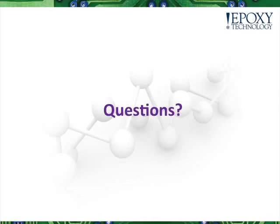And next up, what is the maximum depth of cure for most UV systems? And what is the maximum depth of cure for hybrids? Well, that's going to be two very different questions for the UV systems as compared to the hybrid systems. For the UV systems, it's going to depend on the lamp output. As we talked about, short, high energy wavelengths will have lower depth of cure. They skin over more quickly.